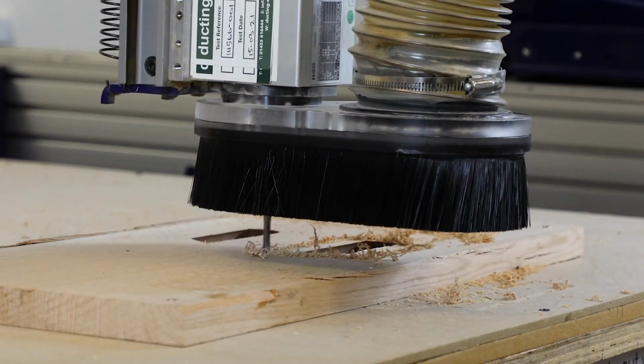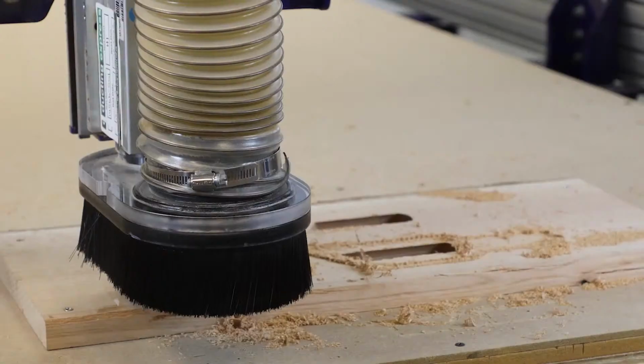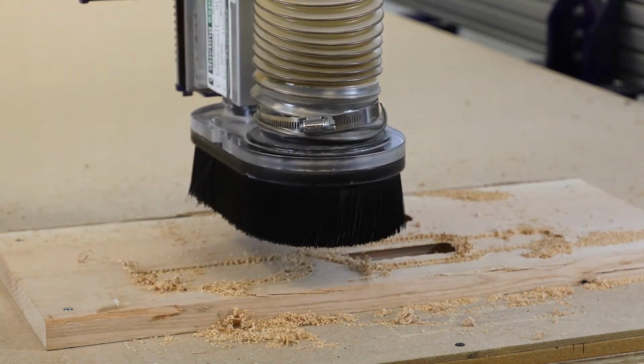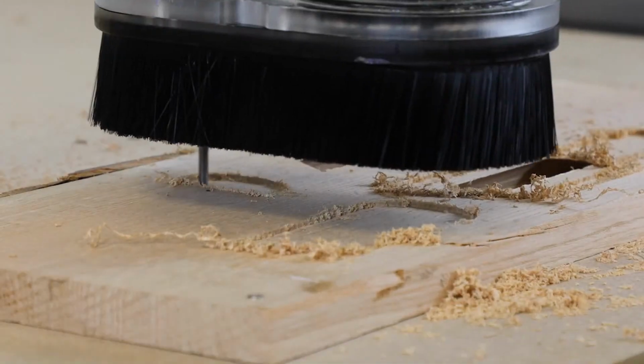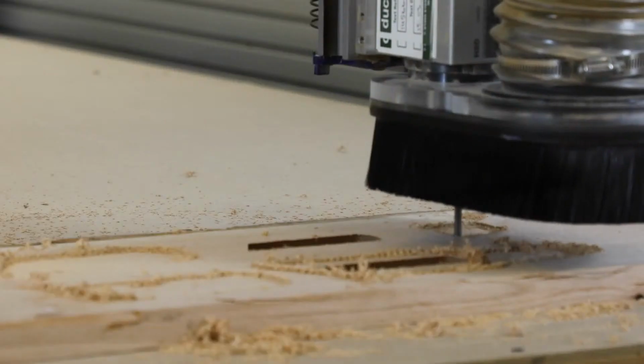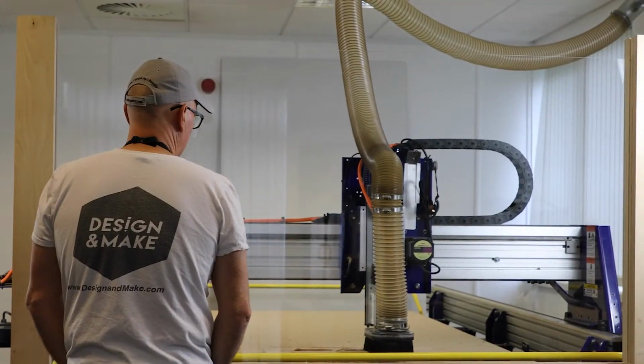So here we go with the roughing of the outside of my bottle. And again, we're going to go down level by level. I guess I was hoping again that this might evenly remove the lion's share of the material, and if I was going to have any warping or bending, then it would be even across my whole part.